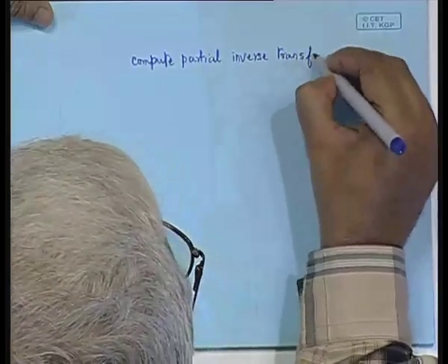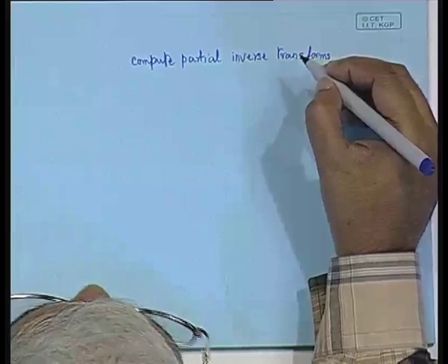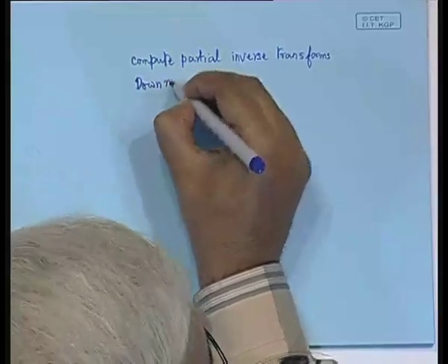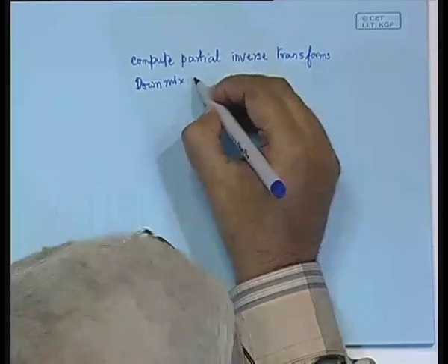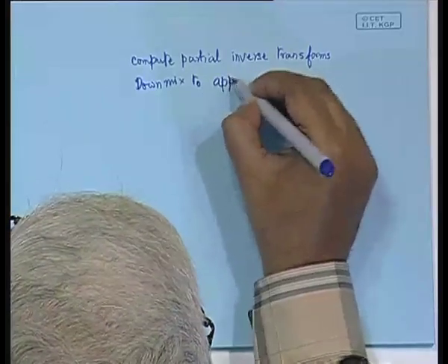In fact, the partial inverse transforms are calculated because the technique adopted in the transformation is the MDCT. So, there is always a partial overlap and add method, which is used in order to get back the original time domain or PCM samples. And then what we have to do is to down mix these transform coefficients to appropriate output channels.